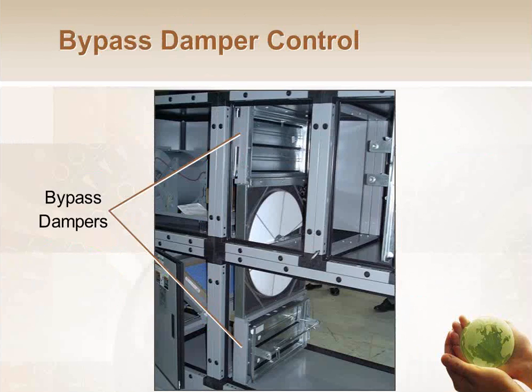This is what that wheel will probably look like inside the unit. One path is going that way, the other path is going this way. This guy's spinning between them, grabbing energy. We will frequently put bypass dampers in there. This one's a pretty small wheel with pretty large bypasses. Sometimes the wheel will be larger, 10 foot in diameter, for example, in which case we'll put the bypass dampers in the four corners. That's another way we might do it to save some height and so forth.